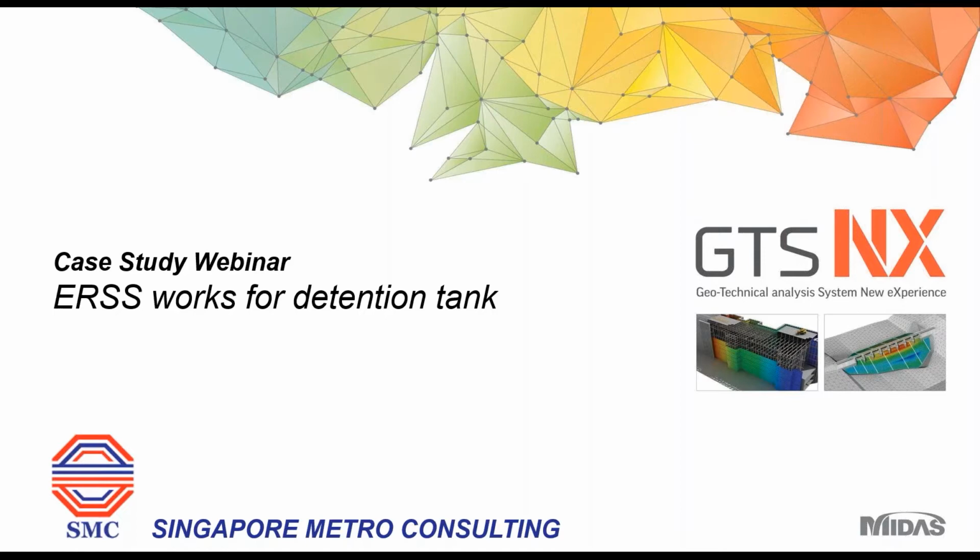And I will use 9 boreholes to assume the ground condition with a bedding plane function, which is supported by the GTS NX program. I will take those boreholes from the SI report, which is provided by our users. And there are 4 layers of soil. The first layer is assumed to be fill, second is marine clay, third is S6, and the rest is S5.